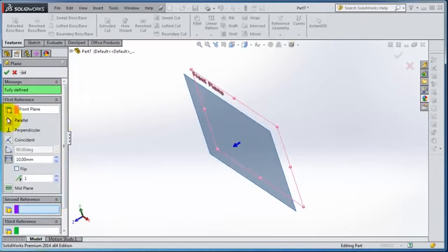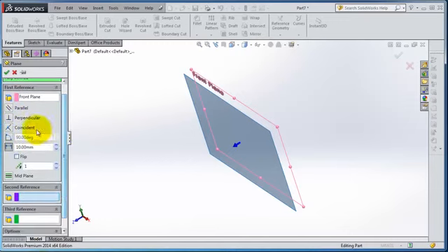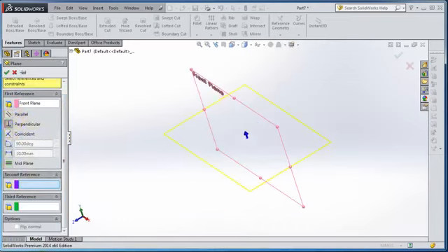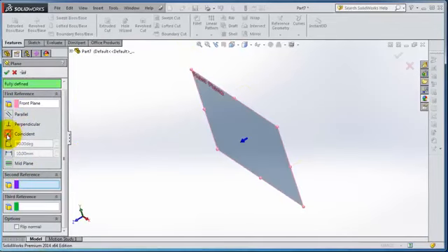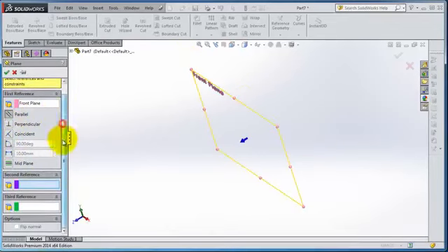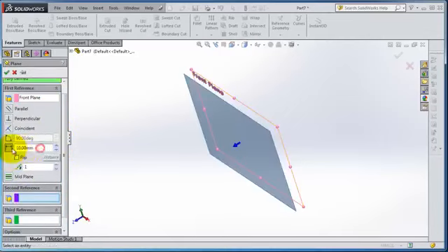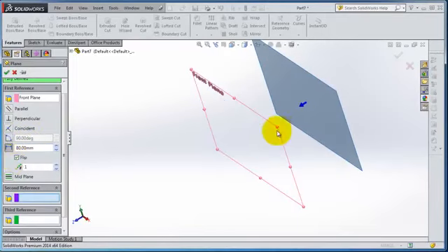menu. So these are the references to create your planes. You will be able to use them in the future when you start creating parts and so on. So you'll be able to have different types of planes, either perpendicular to that plane, or parallel, or coincident. So I want to make it parallel and make a distance of 80 millimeters, and if you click flip, you're reversing the direction. And the number of planes we want, we can insert 4.